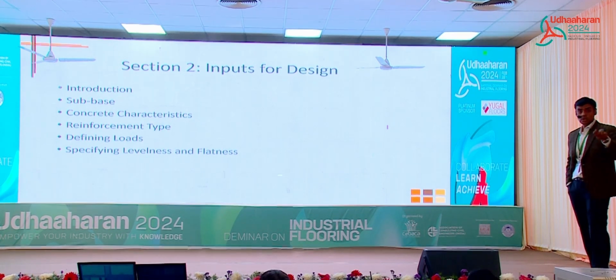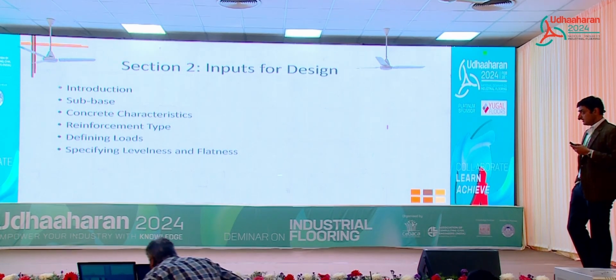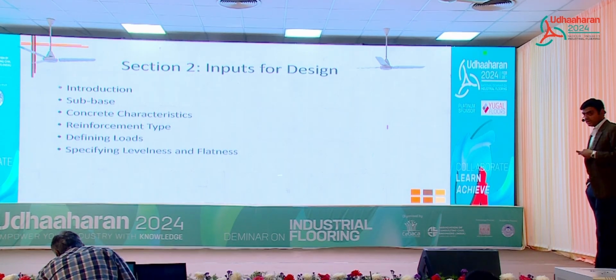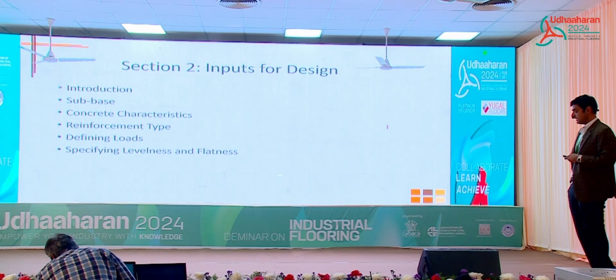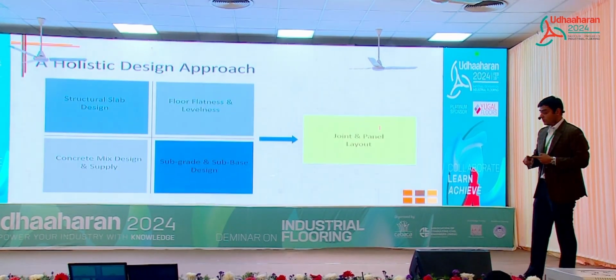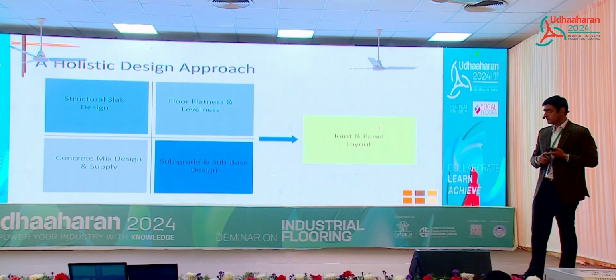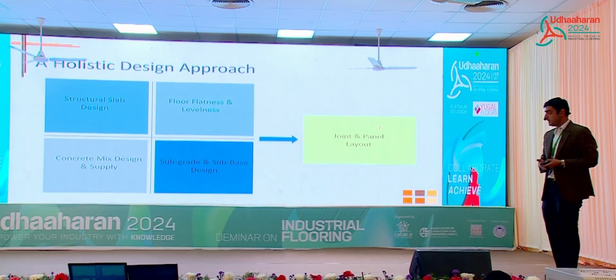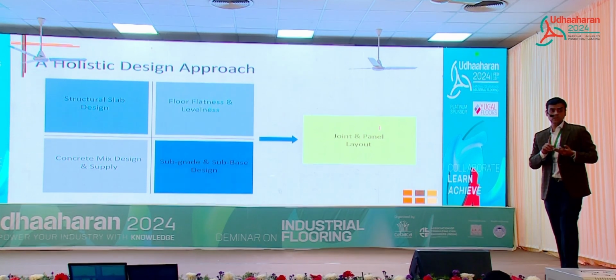Defining loads, very important. How do we define loads? Because this is where we miss a lot of times. Specifying levelness and flatness, again understanding why we need certain levelness and flatness. Concrete mix design, very important, because this is ultimately a concrete floor. And supply, this is what we do not think of often.